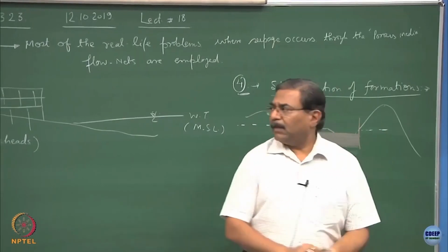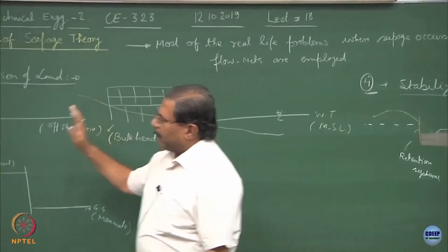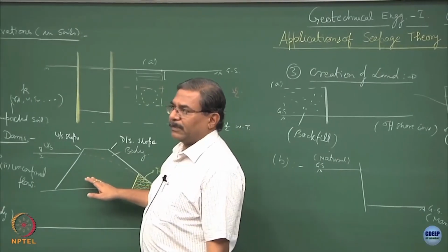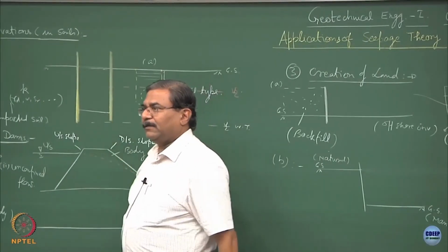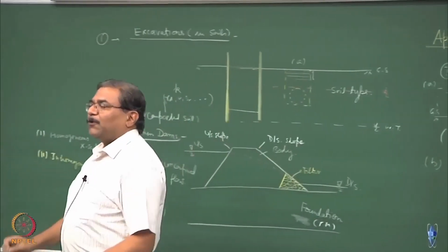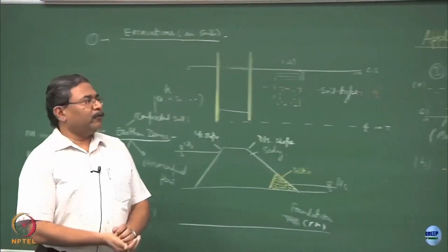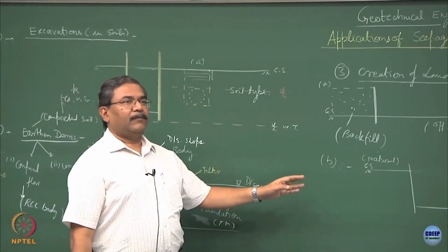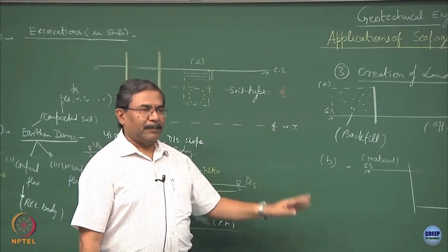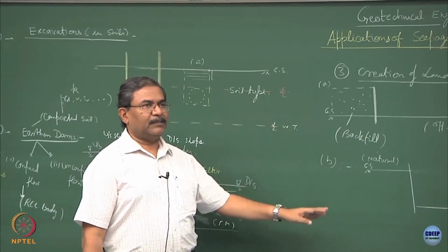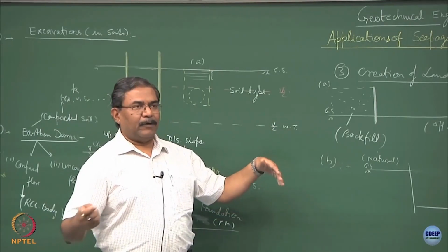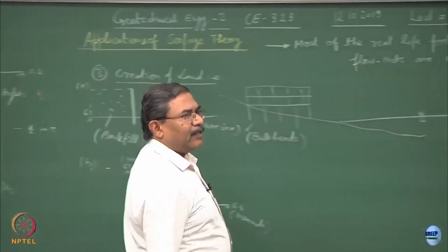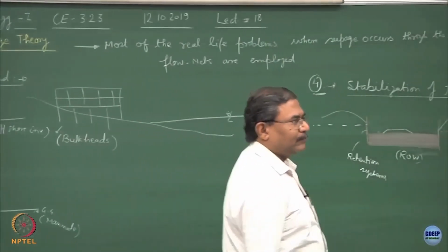And most of the time in all these situations we are dealing with the soils which are in a state of compaction. Is this part clear? So, what I am going to do now is I will take a few situations and I will analyze them for seepage forces, pore pressures, the type of hydraulic gradients, exit hydraulic gradients and what not.